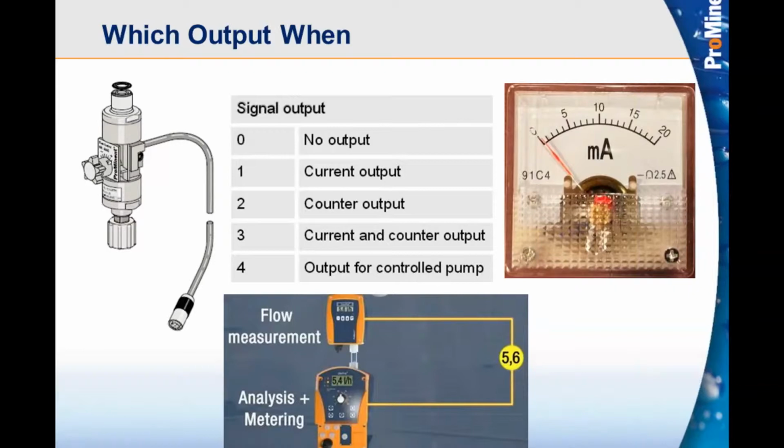But if you see the display on the front of the Delta pump, it's looking to maintain 5.4 liters per hour. So in this case, when that feedback signal comes back, the Delta is going to slow itself down to go back to the 5.4 liters per hour the system requires. So we can have very precise controlled flow from that with the Delta.